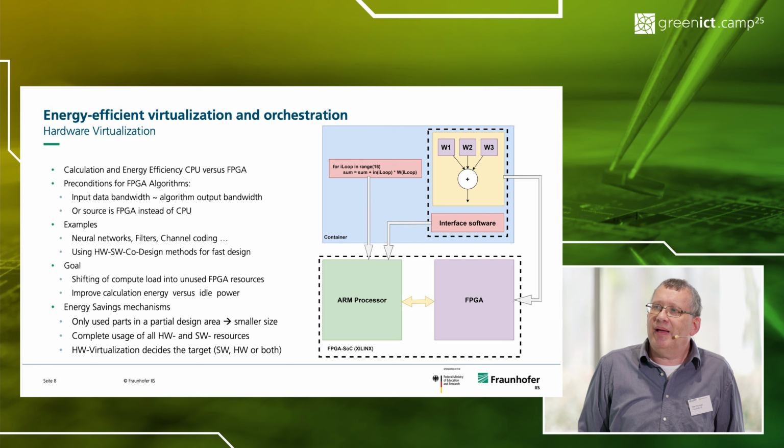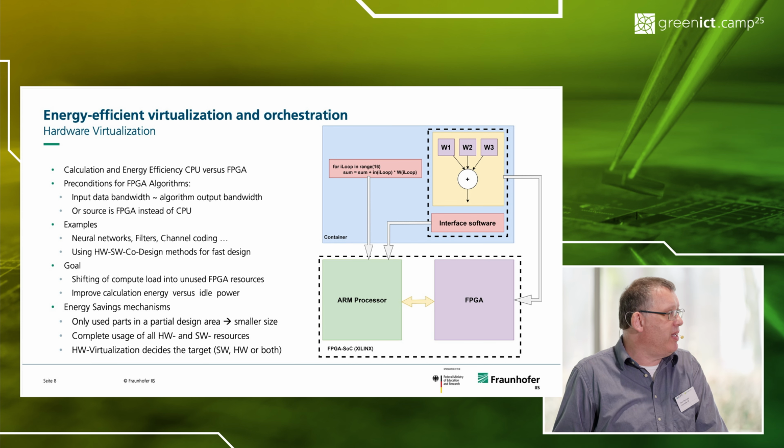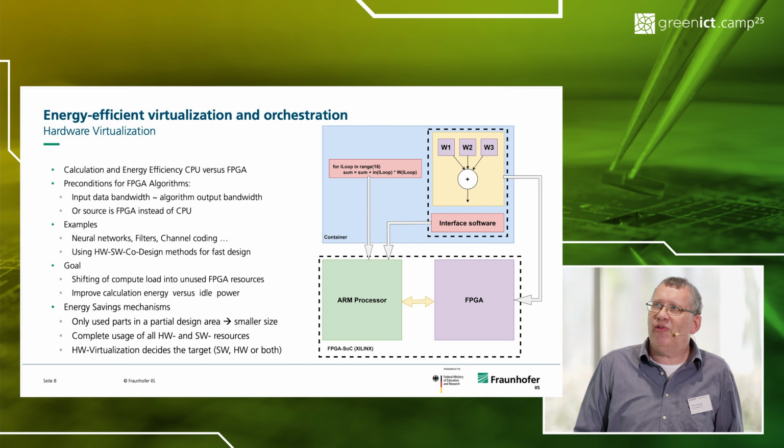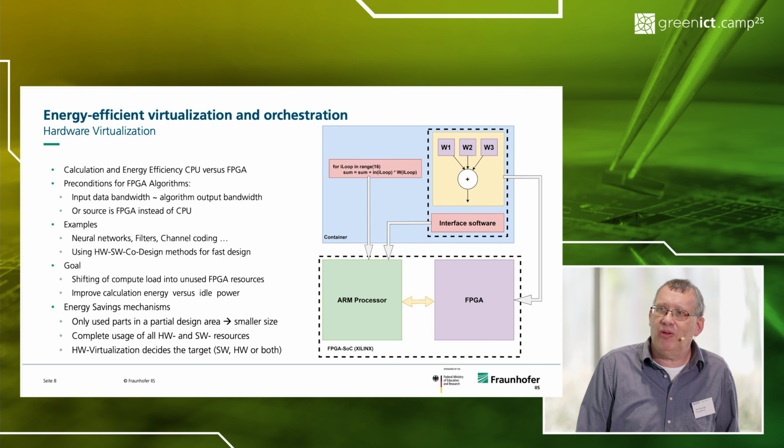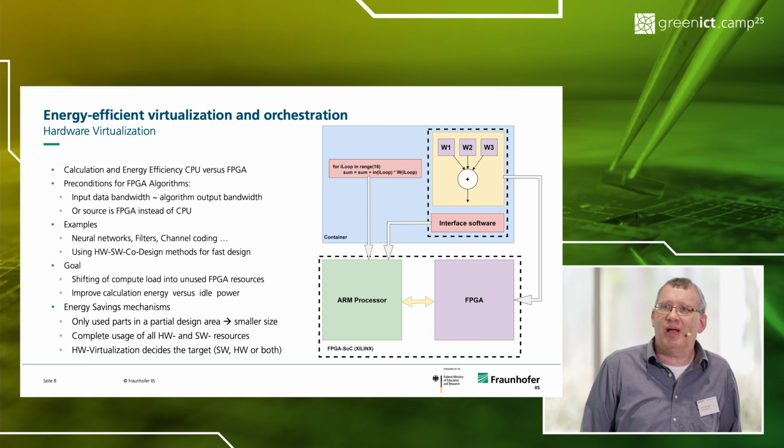And if you realize a hardware solution, then you also need software, because you have an interface between the hardware and the software. So if you have loaded a coprocessor into the FPGA, you need an interface software which is responsible for the communication between the software part on the ARM processor and the FPGA part where you have realized your hardware.